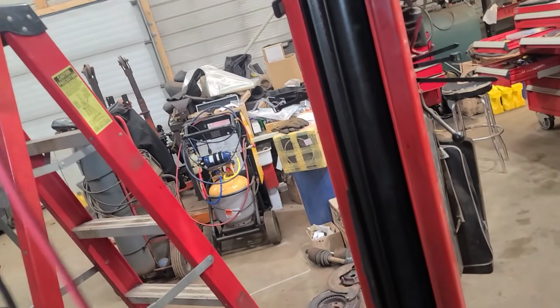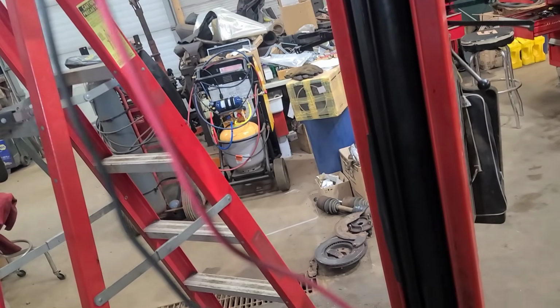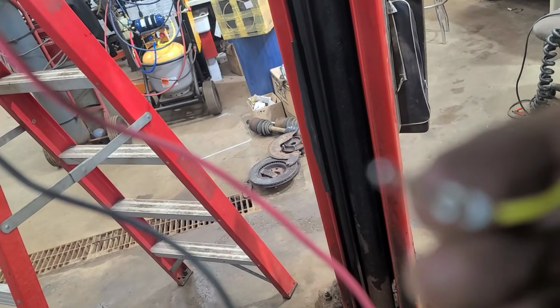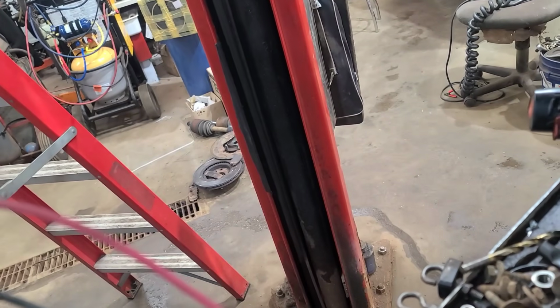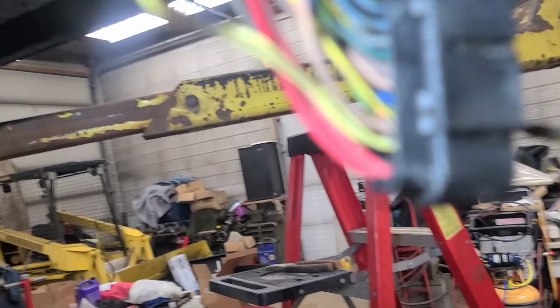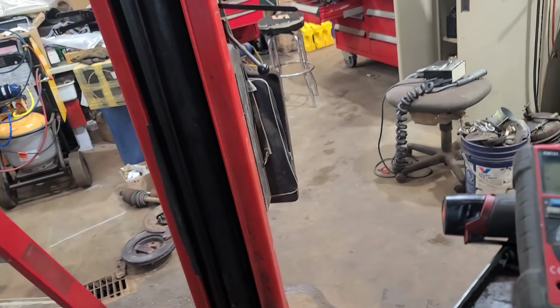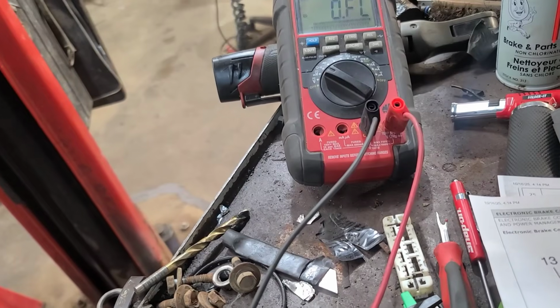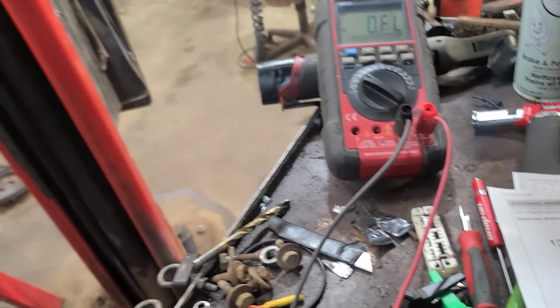I tried to reshape the terminals on these little guys here, but that's nearly impossible. They're so tiny. I still have an open across the 2 tan wires, which is pin 15 and 27, which goes to the rear.